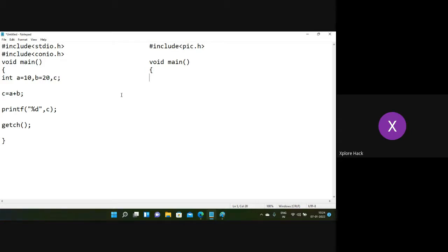So it is very easy if you use the port; you can access 8 pins with a single port. If you go for a pin, you have to identify and configure each pin to work for the specific output. Considering two devices, one input and another output, if you take individual pins 1 and 2, in pin 1 consider we connect a switch, and in pin number 2 we connect an LED.